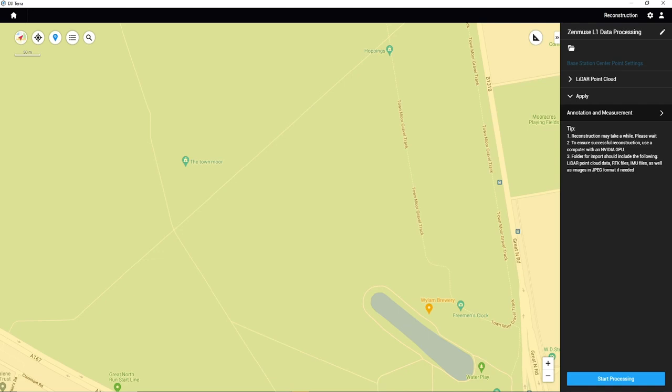If you navigate to the DJI Terra directory and locate the folders where all your projects are saved, they should be listed by numbers increasing from 1. If you delete all the folders you no longer require, this will send them to the recycle bin. So ensure these folders are permanently deleted from the recycle bin to allow the Lidar reconstruction to complete successfully.